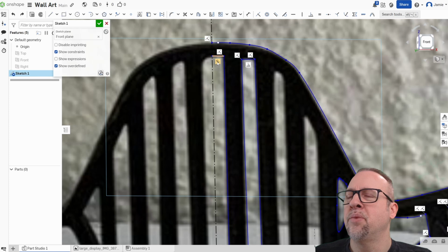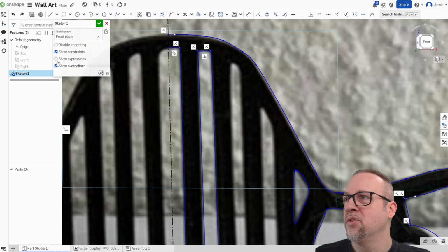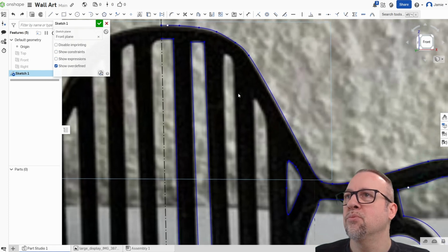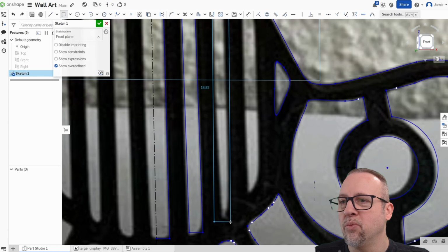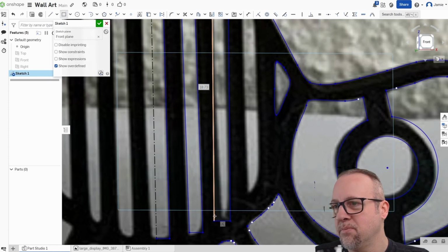So all this is showing that this is equal or parallel to something, and this is coincident to a point. I believe that's what that one means right there, coincident. So if it was showing this symbol, then we know it's a vertical line. So get rid of that because it just makes more mess. Back to square, actually we can create a nice square, and then we can adjust that edge up there, and we can notice the square wants to be perfectly vertical.